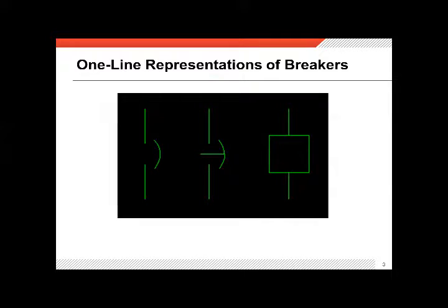Okay, the first thing I want to cover are a couple representations of circuit breakers. On the screen now, there are three ways that we can show circuit breakers in drawings. The first one is really mimicking a molded case circuit breaker, and I don't think that would be terribly appropriate for a substation drawing. The second one is actually mimicking an old oil breaker.